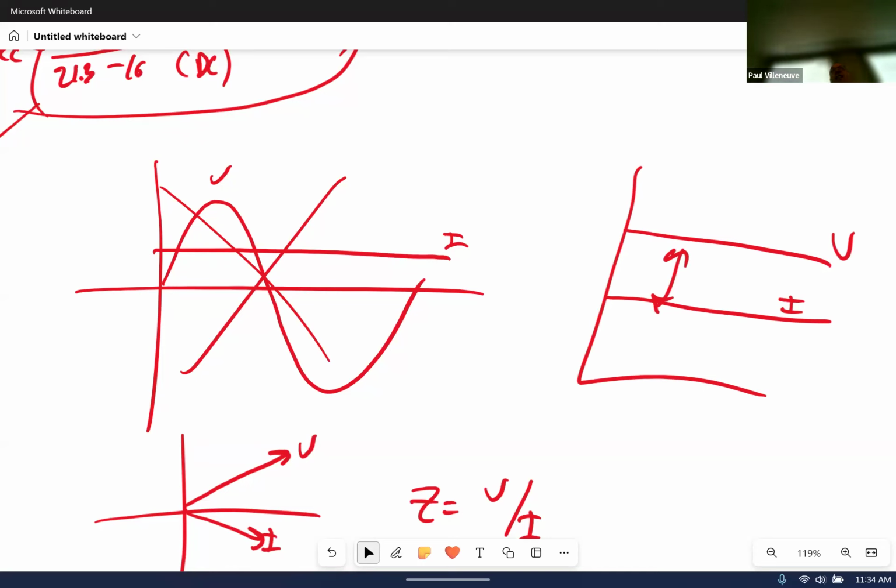C dV/dt, L dI/dt, you have to take derivatives. That's not a fixed resistance. That's an actual derivative. So if something's changing, you can include that, and that would mean your impedance changes. So introducing steady state allows us to take that changing part out of it, so we can calculate impedances. So both parameters have to be AC.